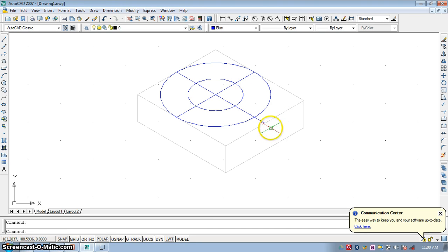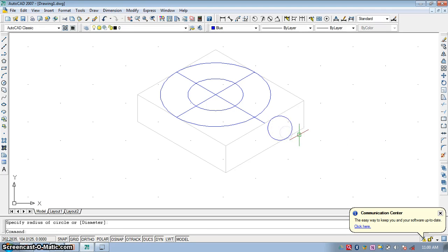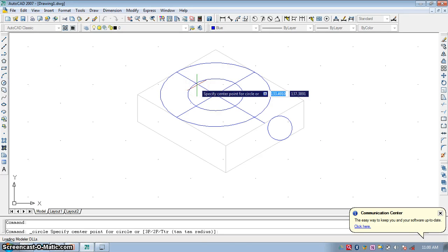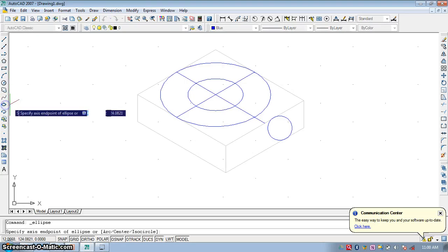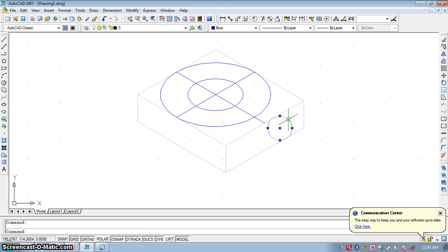Suppose you want to draw the circle in front view mode, then you have to change the mode. Let us take F5. So the front view circle should be like this. If you draw that circle in front view mode, let us take I, enter, and if you draw it into the top view, that would not fit. It looks like this. So that should be in front view mode, and when you draw in the top view, that should be in top view mode.